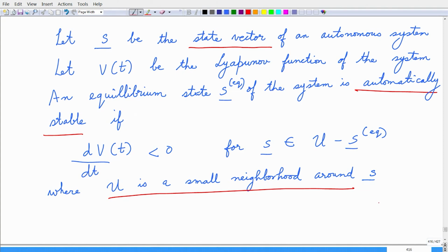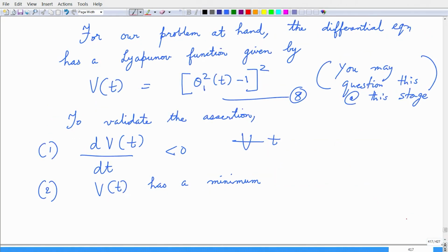Now the question again is how to get this Lyapunov function, and that seems more like an art than a theory that gives you a Lyapunov function generally for nonlinear systems. We do not have such a theory here. But if you can show the existence of a Lyapunov function and then proceed with the analysis, we can guarantee the stability of the nonlinear system.